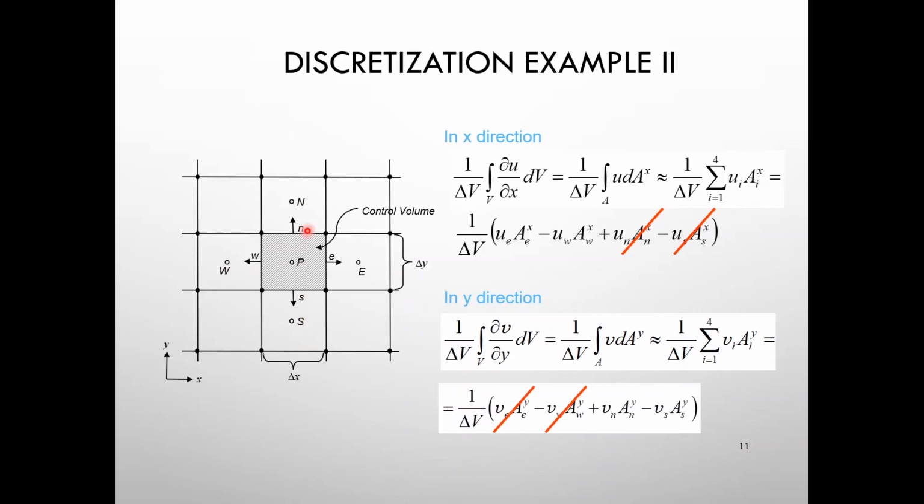So whatever the variations, there is no u velocity towards the y directions. There is no u in the y components. So we take this as, okay, one needs to get in and one needs to get out from the control volumes to make sure that the continuity equation is fulfilled. So one will be negative, one will be positive. Negative means that it is going in, and positive means that it is going out.